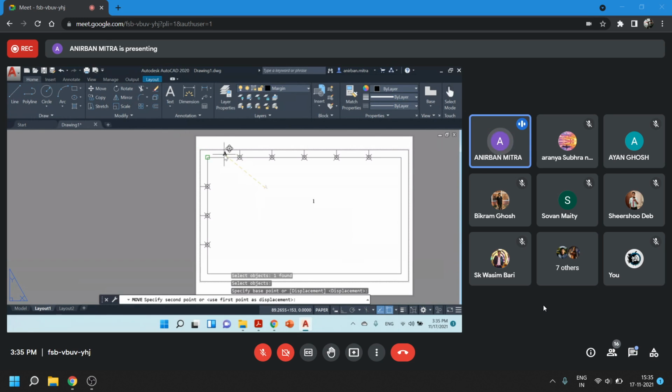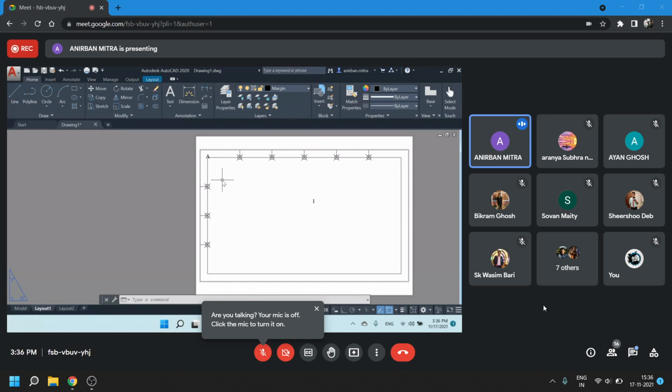Now, if I move it here, do notice that the end point of the line to the left of it, that means the vertex or the corner of the rectangle, is now being selected by O snap. You can see a green square over here. So if I now click here, the A will move to that location. You can see what has happened. It has moved to the corner. So it is a good idea to switch off the O snap mode at this point. So I'll just move back, Control Z, let's undo, and switch off O snap, and then move this letter.